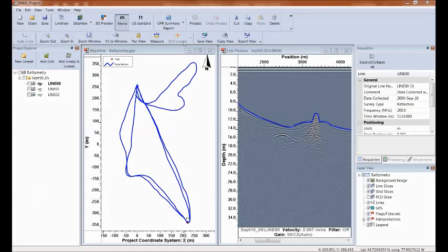So my option here is to output it as a CSV file. If I take all this and output it as a CSV file, I have that polyline information from the bottom of the lake. In the polyline, I have all the details: the latitude, longitude, and the depth. And from that, I can generate something like this.